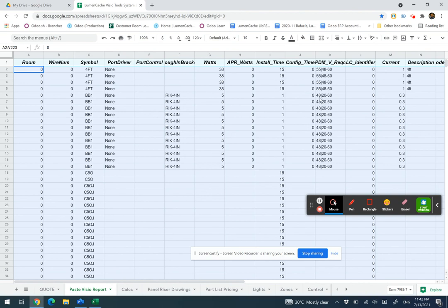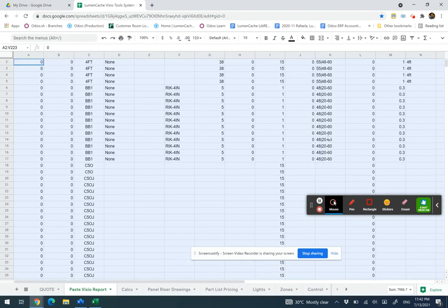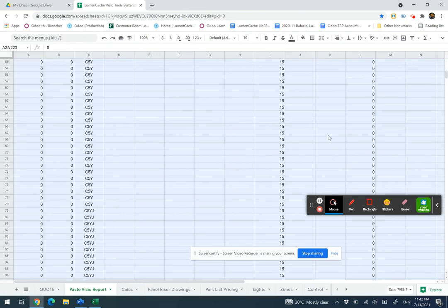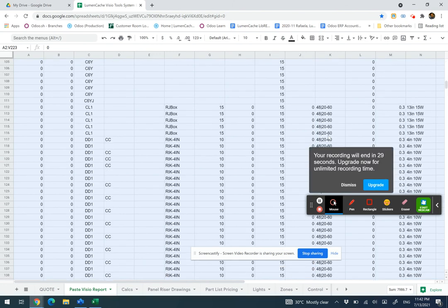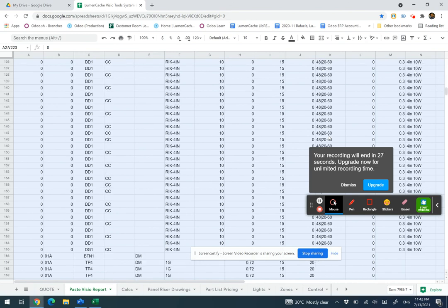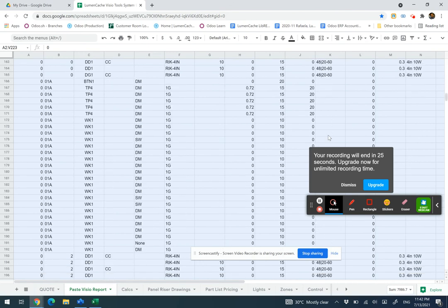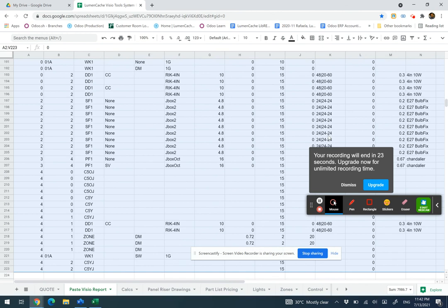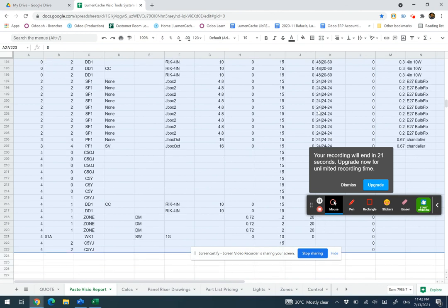So for example, this one prefers 48 volts, but it works between 20 and 60. And then there's some devices like strips and bulbs that may have a very specific voltage that they need. So for example, 24 volts only, indicated by this, it's 24 volts regulated and it requires 24 to 24 volts. So these particular things are calculated automatically.